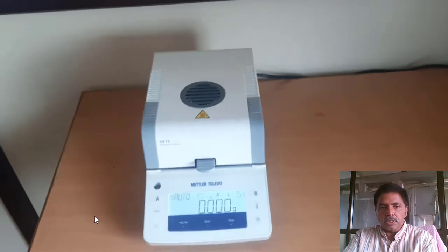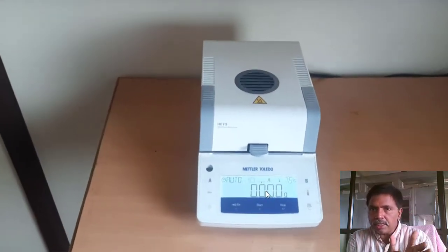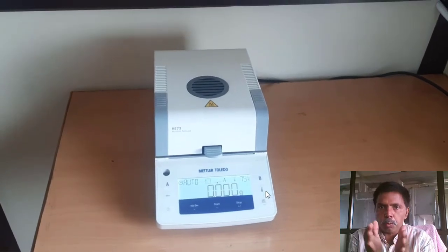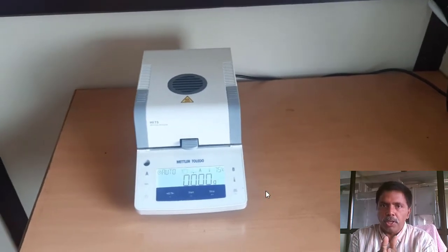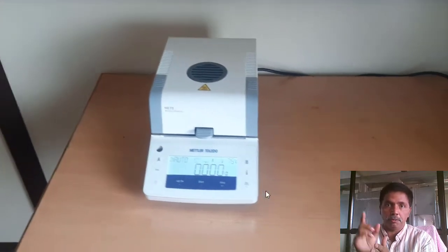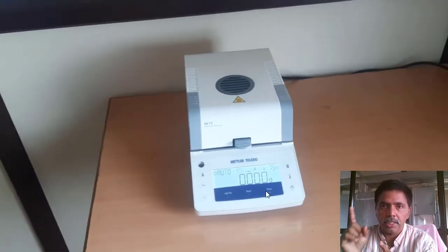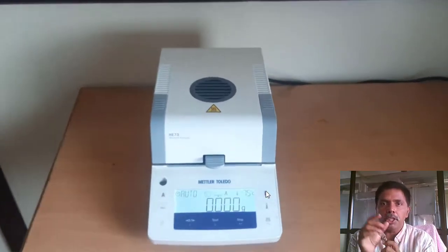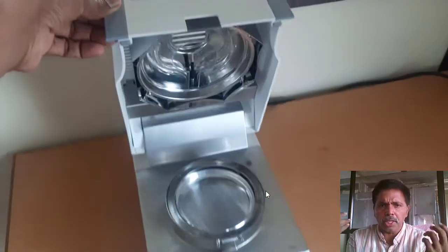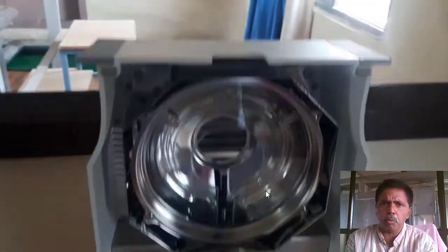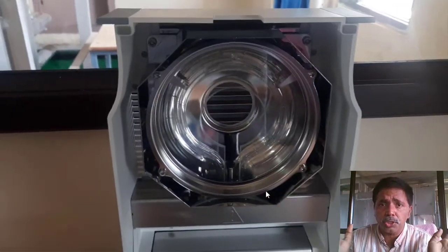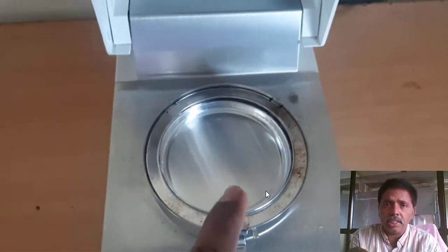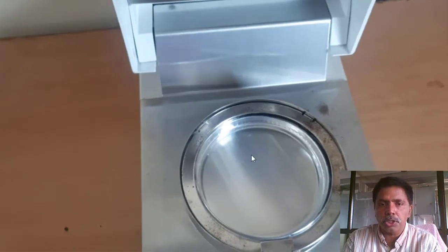And now I will show the designing of solar dryers. First, whatever product we want to consider, we analyze the moisture. The first step in the design of dryers is analyzing the moisture of that product. For example, tomato, green chili. Why? Because tomato is not one type. Hundreds of types of tomatoes, green chilies, and onions are available. For whichever product we want to design, first you select it and analyze the moisture using the moisture analyzer.